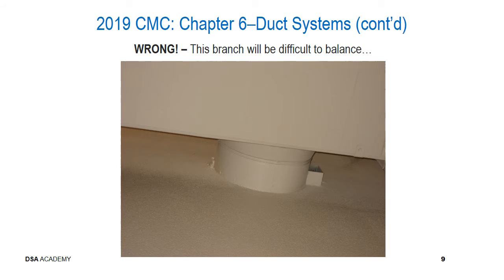The picture on this slide shows a situation where the actual sheetrock and the wall finishes are going to impede the ability for this damper to even be adjusted at all. As you can see on the left-hand side of the picture, on the round ductwork that's penetrating the wall, the actual nut on the other side is completely enveloped in sheetrock mud, and there's just no way that this damper is going to be able to be balanced or moved to balance this system.